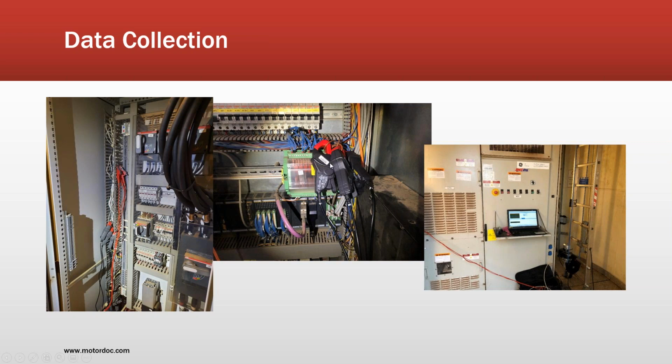So if I connect 1, 2, 3, I put on 1, 2, 3, because part of what the software does when it's analyzing is convert everything over to kilowatts and air gap torque. So once it's hooked up, you push a button, and 48 seconds later, it tells you exactly what it sees.